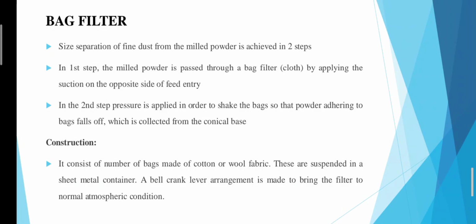Construction: how the bag filter is constructed. It consists of bags made of cotton or wool fabric. These are suspended in a sheet metal container. A bell crank lever arrangement is meant to bring the filter to normal atmospheric condition.